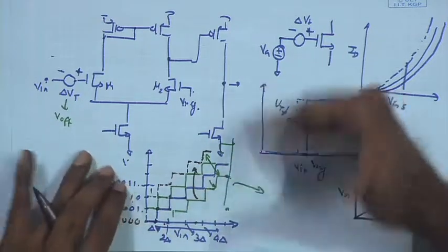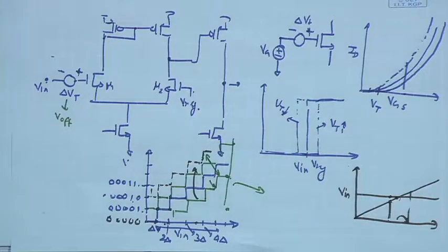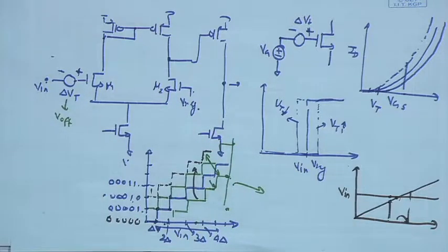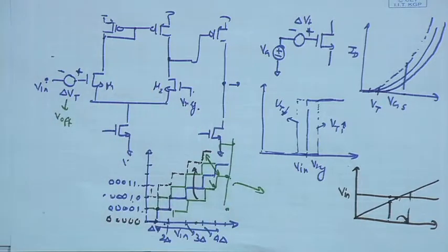And likewise, 2 comparators being used is also aggravating our case. So, it is important to consider this concept of offset and the techniques to cancel that offset, which is in general applied whenever we are targeting significant precision in our data processing. Along with the single ended version, we will also look into the fully differential version, and try to see how it can benefit us. That is another reason why fully differential operation is advantageous. For the comparator, we will see that if you are using the fully differential version, offset cancellation can be more effective or more convenient to implement.